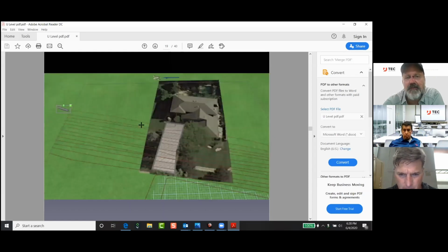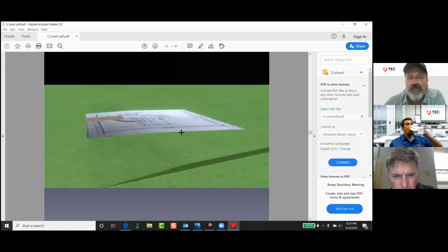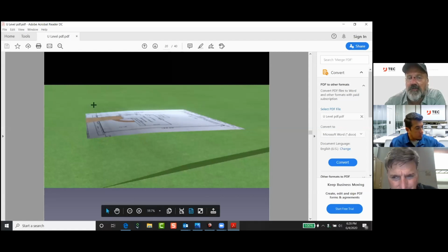It's finally here. There's my house with a driveway, same contours, and you can apply it to anything. Once you put the contours in and you ask your homeowner for their plat of survey, once you import the survey onto the contours, you can see it warps the survey to meet the contour readings. The contour readings take over and the plat of survey melts to those lines.